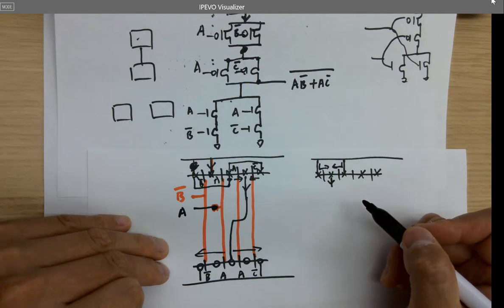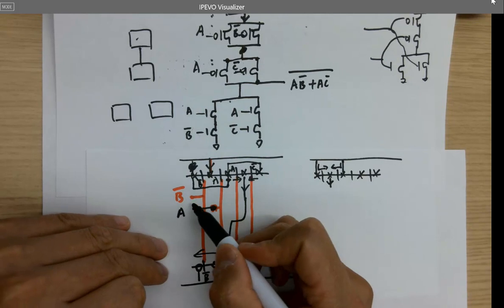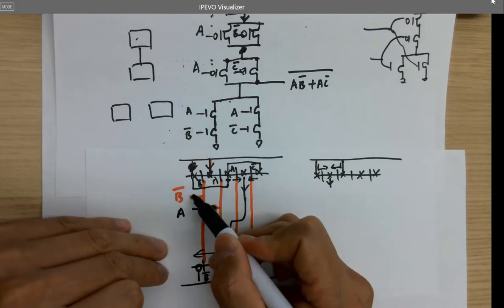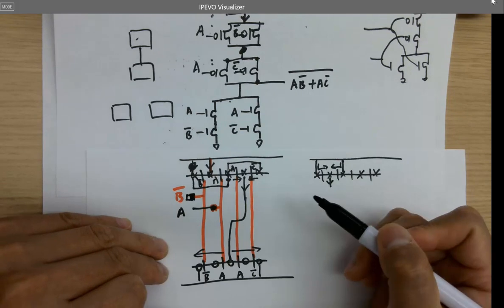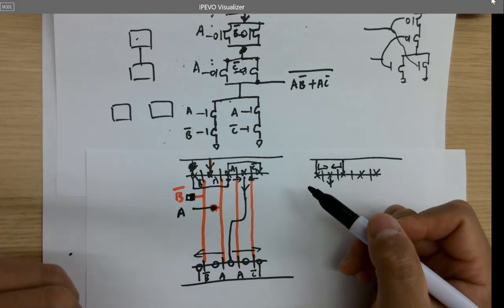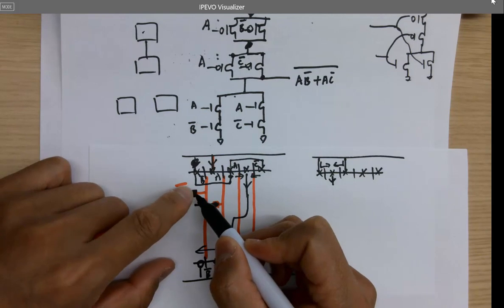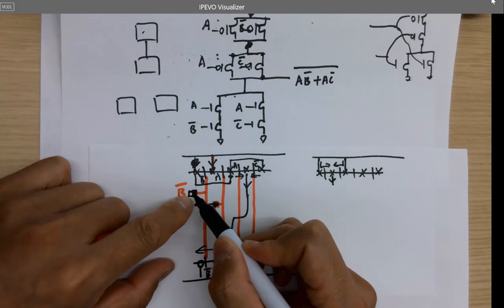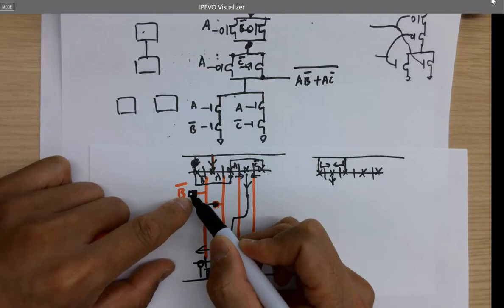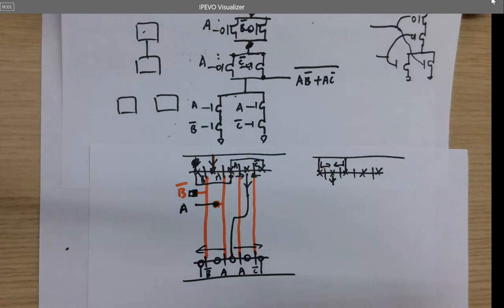Is it bad for the inputs to be on different layers? No. But eventually you have to use metal 1, even though you use the poly here, but you still have to have a metal 1 node and have a little piece of metal 1 here. Because you put a node here, or there's a signal input just next to this gate. So you have to make it ready for getting connected to other metal wires. So use metal wires to route all the signals, right?